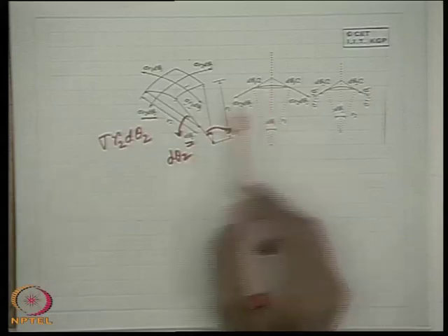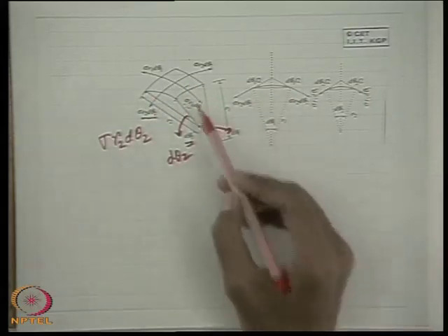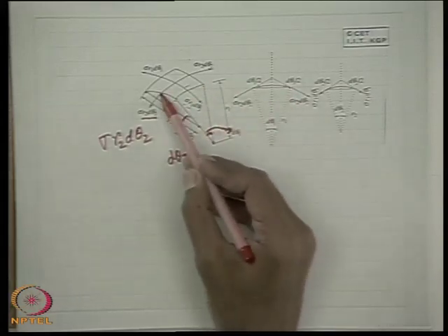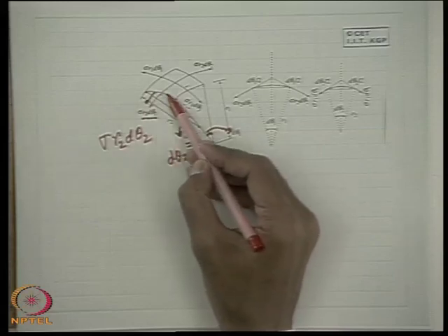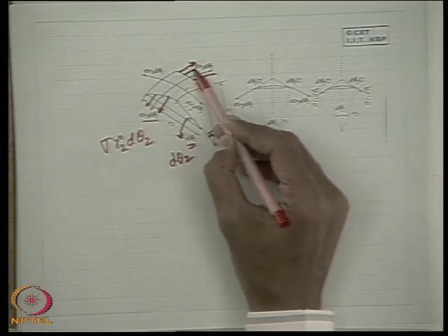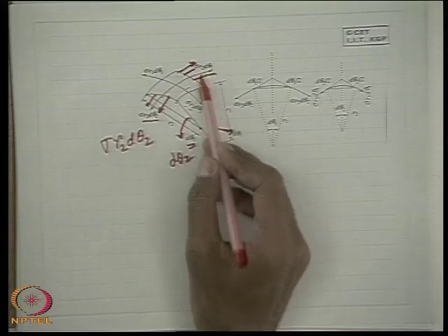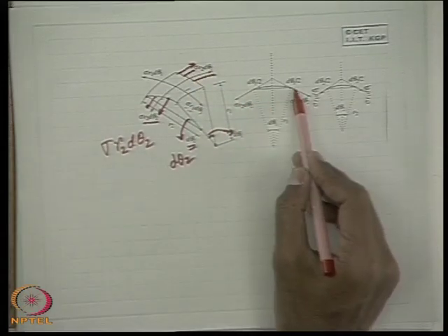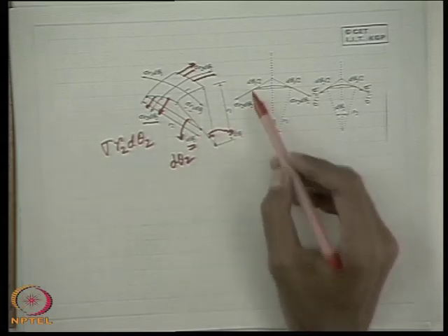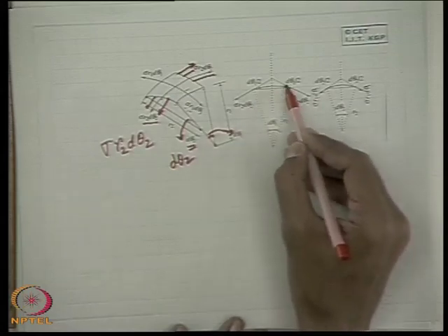Now this is a three-dimensional view. If you look at the two-dimensional view, from this angle we see only this part of the curve, where these forces act. I am showing it by only one arrow, sigma R2 d theta 2, as all the forces sum up to this. From simple geometry, this is d theta 1, so these angles will be d theta 1 by 2.